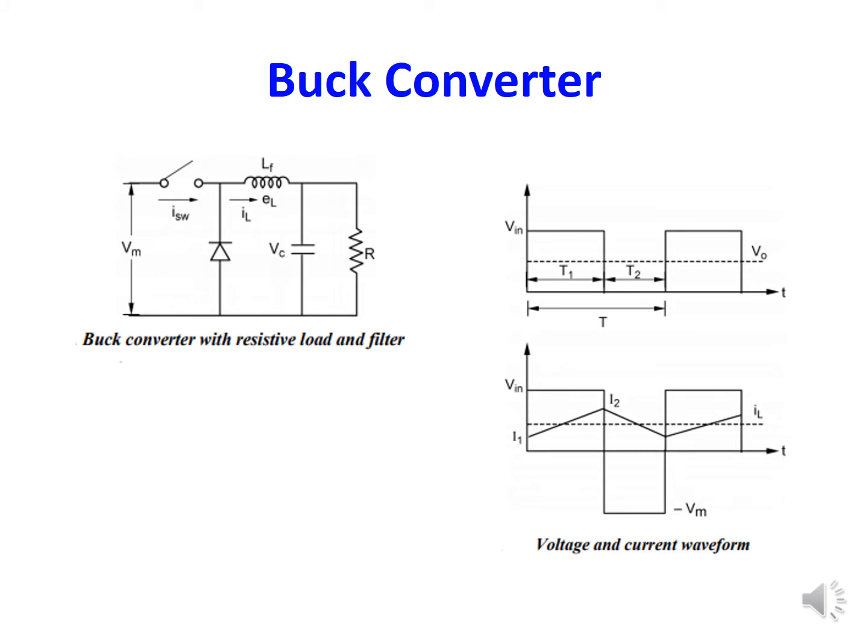Buck converter can also be referred to as a step-down converter, which produces lower output voltage than the applied DC input voltage. The buck converter has two operating modes depending on the switch being on or off. First, let us consider switch on, that is, closed condition. The diode becomes reverse biased and the input voltage causes a current to flow through the inductor. This charges up the capacitor.